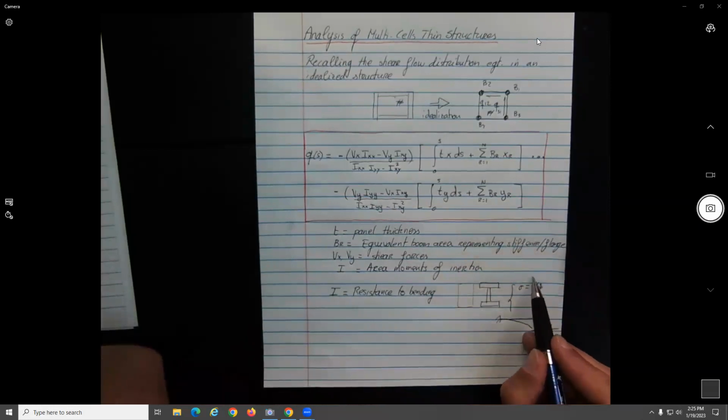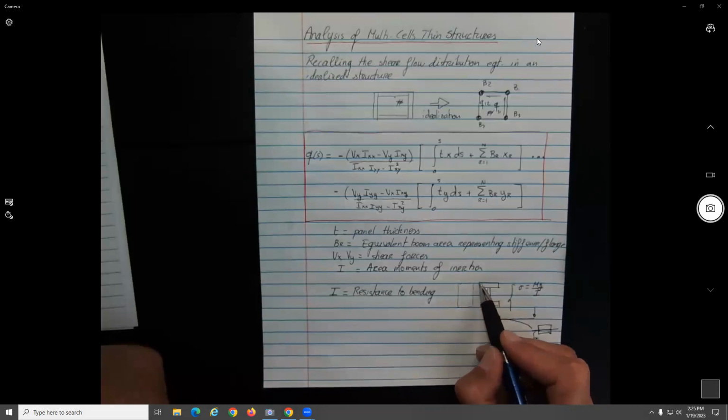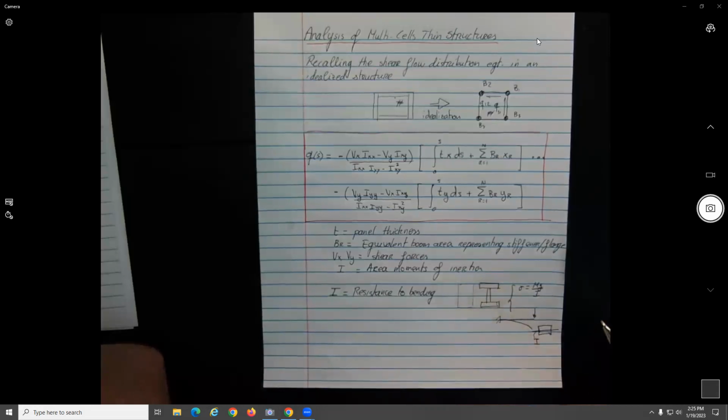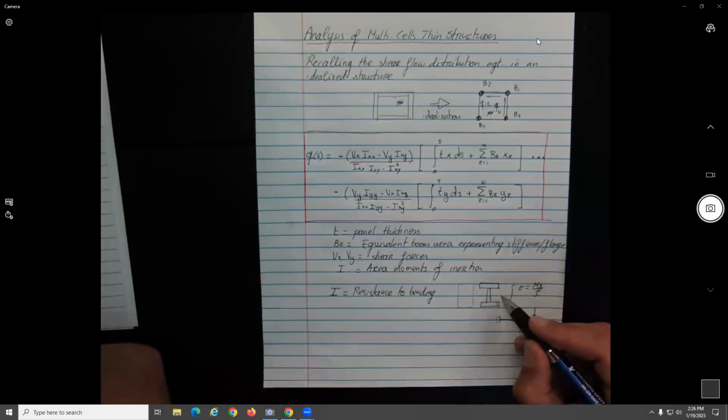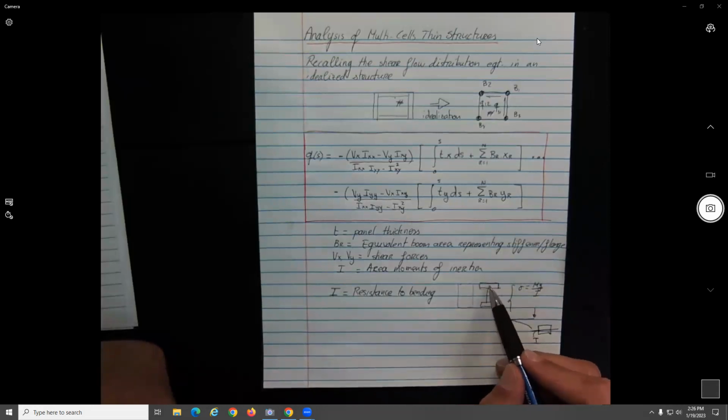Let's put it this way. What is the distribution here of the bending stress if we follow this equation? It is zero at the neutral axis and bigger at the top and the bottom, no? So where do you want to have the material? Most of the material at the top and bottom, no? And what is the assumption you are making with this? That the structure is not going to break due to shear, because what would be the shear maximum? Maybe you remember this one. The shear generally would be maximum at the center, no? But if you just look at bending, you want to have the most material to resist the stresses at the top and the bottom, no?